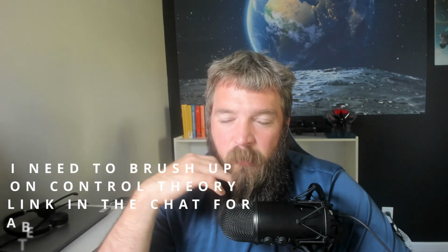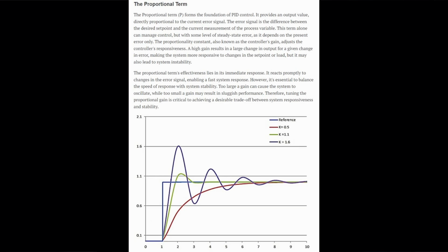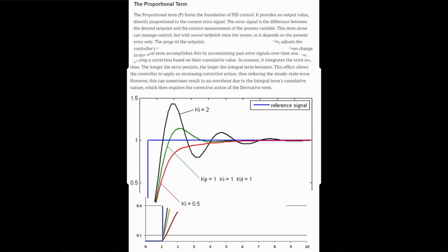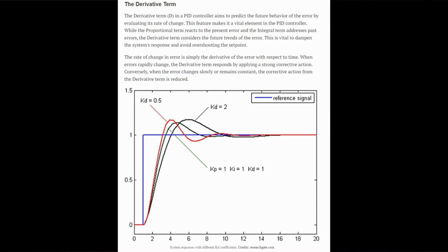A lot of these control loops use what is called a PID, or proportional, integral, and derivative control loop. Proportional is just the standard how it goes. Then you have integral, which bases future reactions upon past events, so it better corrects for overshoot, or gets it into a more stable condition quicker. And then finally you have derivative, which tracks the change over time, so it can better predict future movements. You combine all three together and you get results like this.